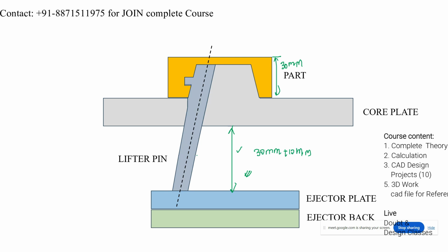But for example, if I am using a return pin, then for the return pin I have to use a spring also. So sometimes I have to take 15 or 20 mm clearance, because there will be a spring here. Understood? Yes, sir. Okay, sometimes we have to take that.